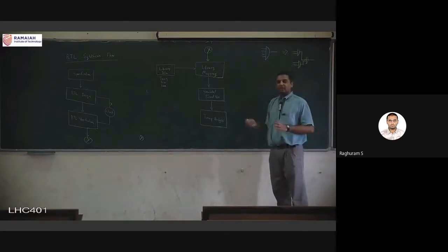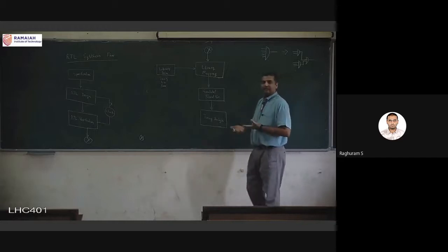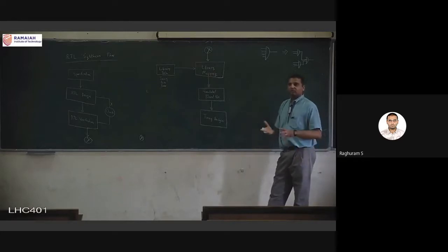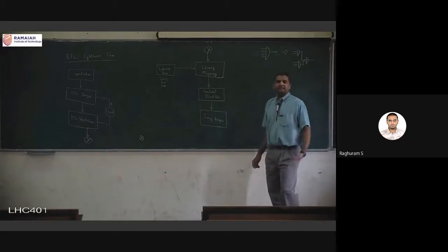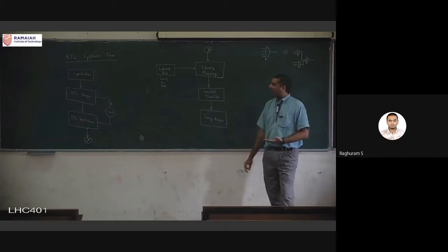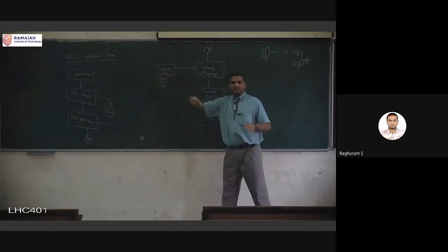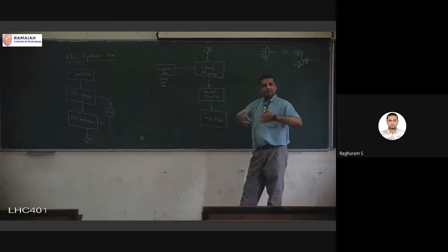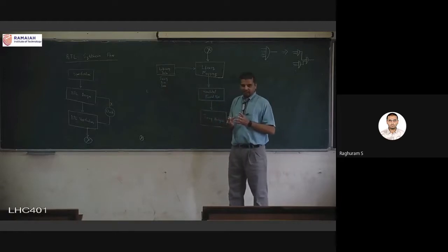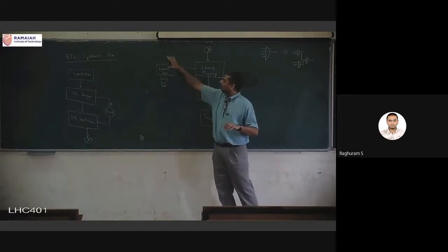That is, some engineer has sat and done this. I know a few people who are doing this type of work because suddenly they have a new customer. For example, in automotive, they want some type of integrated circuit. So somebody is creating a library cell so that every time a new integrated circuit is required by some automotive industry, they can use this data. That is, the engineer is sitting, drawing the layout, performing the simulation, and generating these 3 numbers for that particular layout. And all those together will form part of the library data.